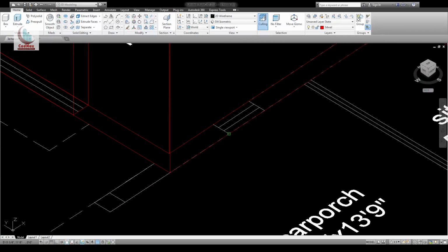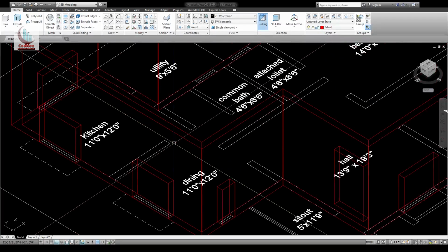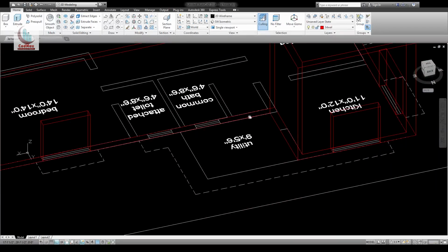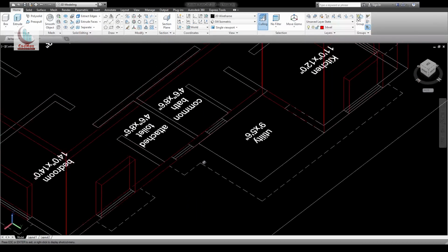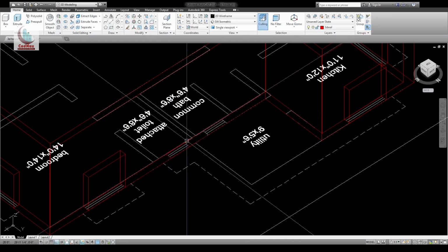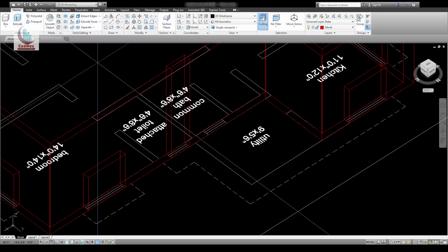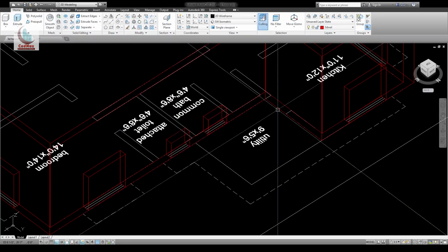Here there is a smaller window. Draw a rectangle, extrude. You can type L, L is for last object. This is the last object drawn, so it will be selected. Enter 4 feet 6 inch. Okay, now press shift and the scroll button and go to this view. Draw a rectangle, extrude that by 2 feet, copy this and place it here.